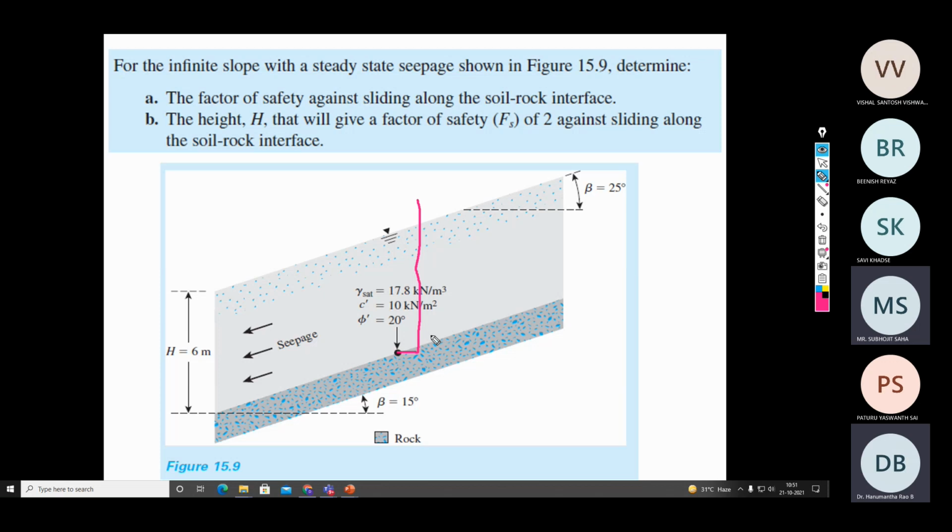Suppose from this dot point, you draw a horizontal line from the top of the point, wherever this horizontal line cuts your manometer, that should be the rise of water level. So this is the height of the water. How do you determine this height? There is a formula that we have derived. Yes, sir, 5.5 meter.